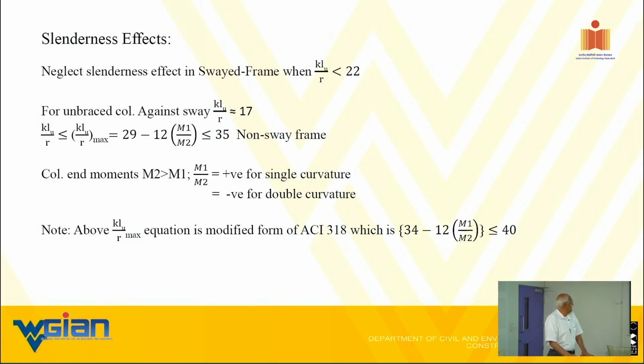And we briefly talked about it yesterday. Somebody was asking me a question about it. This is the ACI equation, that is modified in this fashion for GFRP. This is the steel. You can see the reduction. Obviously, that is coming from the lower modulus of GFRP.